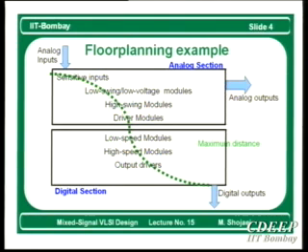Just as an example, I want to design a floor plan of a mixed signal circuit. I have an analog section, I have a digital section, and the digital section has high speed and low speed modules. It has drivers which go onto the pads and then drive output signals.